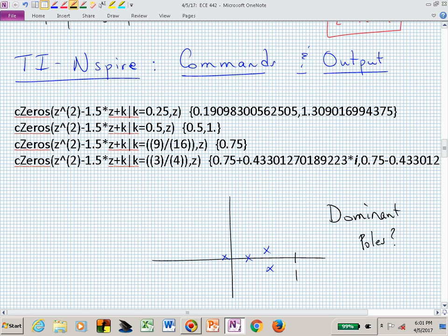So what we will possibly do in this class is pick two poles that satisfy our design specs and then locate all the others conveniently at z equals 0, at a fast location. In this case, the dominant poles in this picture are those two. You would be worrying about their radius and their angle to give you settling time, peak time, and percent overshoot.